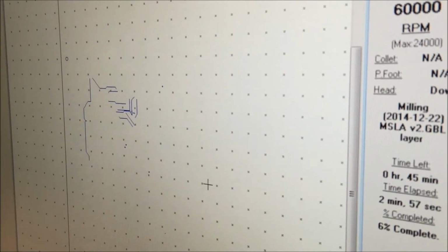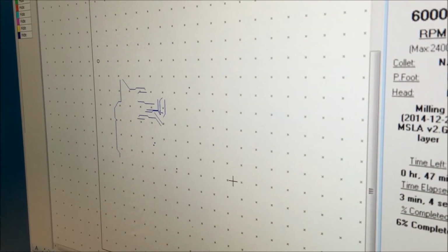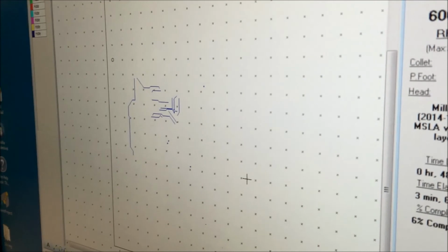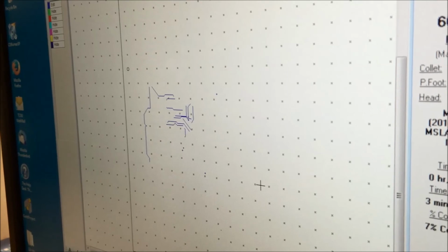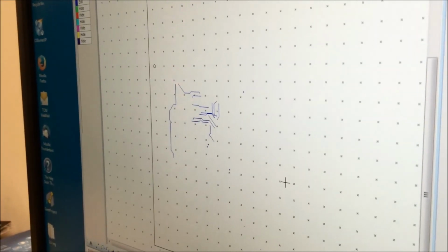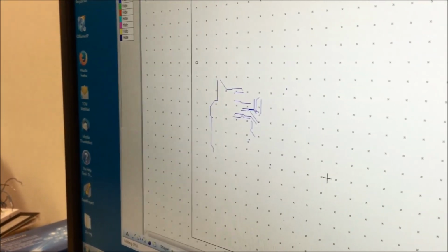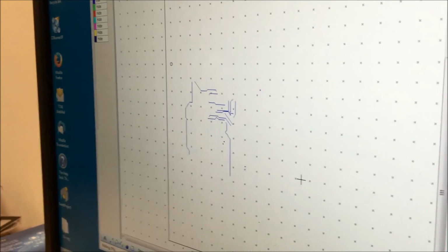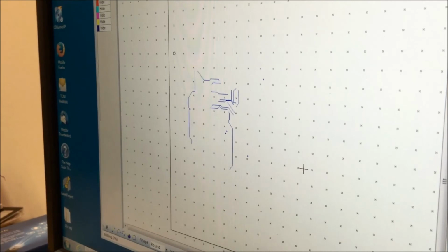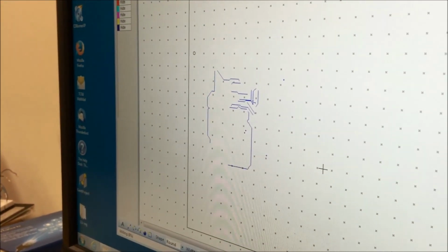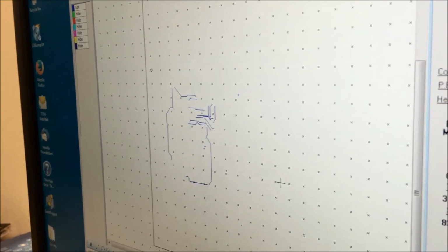And I see that there was no separate step to convert from the traces to the milling away of the spaces. So like, in order for this machine to work, it takes every copper trace, negative, right? It's like sort of a negative, it has to make an outline. It has to isolate every trace. Right. And there's no separate step. You just tell it to take the Gerber file and implement it, and it figures out that isolation without a separate operator. That's my understanding of it right now.